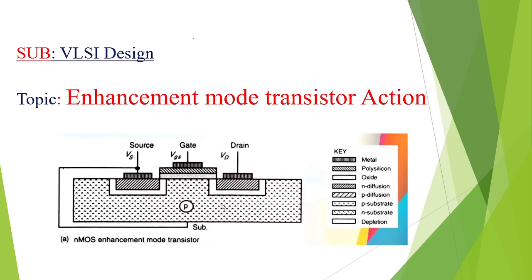I'm going to explain enhancement mode transistor action. Enhancement mode means there is no channel between source and drain while fabricating a transistor. Some extra supply is required to form the channel from source to drain. So we can see this.